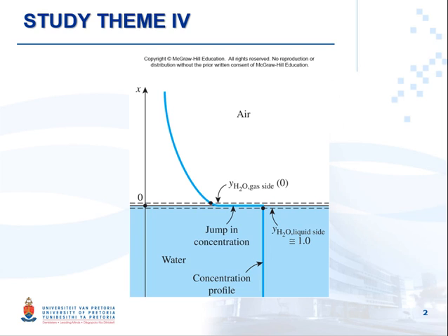If you remember from heat conduction, we had two very usual types of boundary condition. We had either a specified temperature boundary condition, a specified heat flux boundary condition, or an insulated boundary. To find the concentration distribution, we need to find comparable definitions for these three boundary conditions.